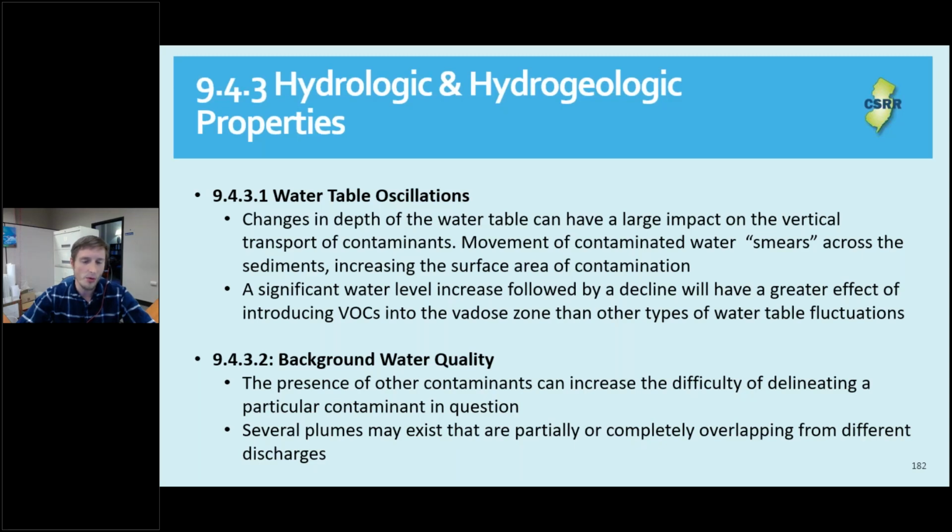We also have background water quality. The presence of other contaminants can increase the difficulty of delineating a particular contaminant in question due to the number of dilutions required. Several plumes may also exist that partially or completely overlap from different discharges. Next slide, please.